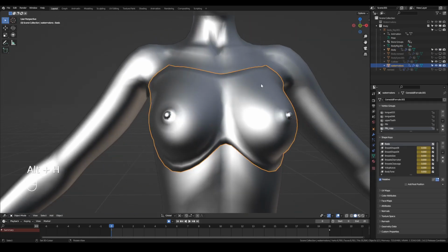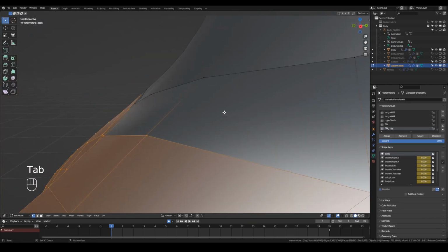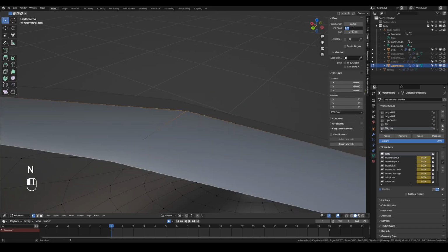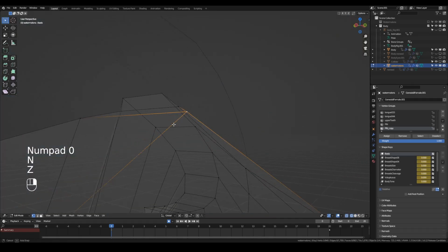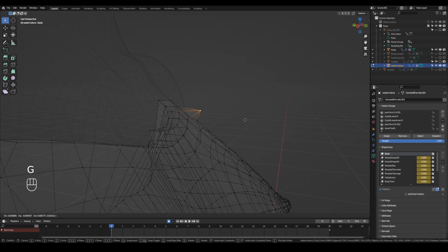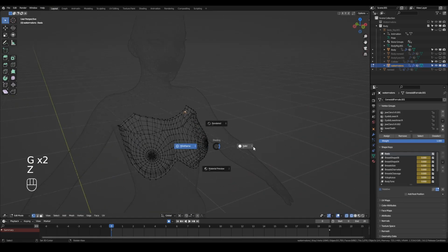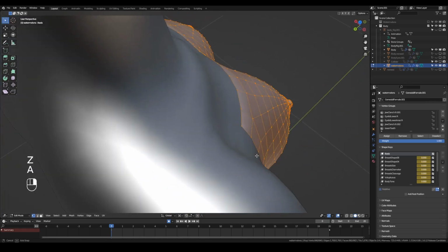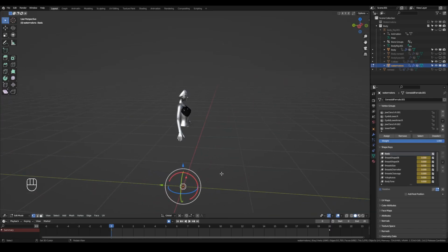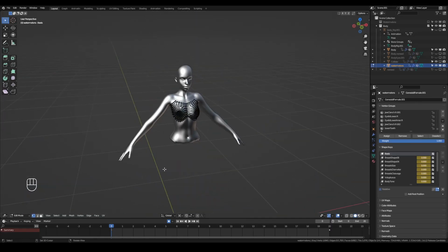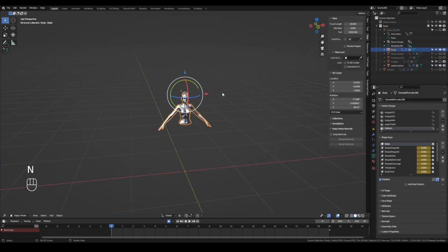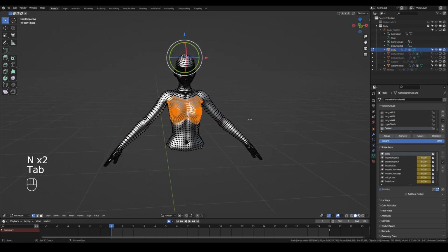Now the hardest part. We need to make our mesh larger than the rest, apart from those vertices that will be driven by our simulation. As you can see now, the vertices are in the same position, but the simulation mesh must cover them. The only rule is that every vertex must be as close as possible to its part, because when we want to make a big simulation, the vertices would have a bigger distance. When they move from the initial state, the distance between them would scale also, instead of being offset. In other words, the volume of the simulation on the main body would be smaller than the actual simulation. So the closer the vertices are to each other at the moment of applying the mesh, the better the end result.